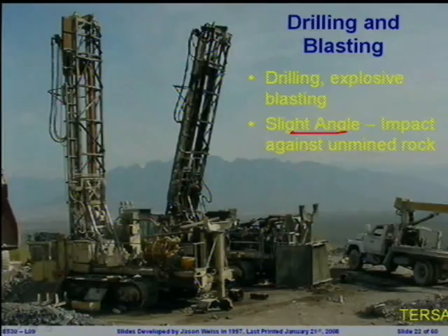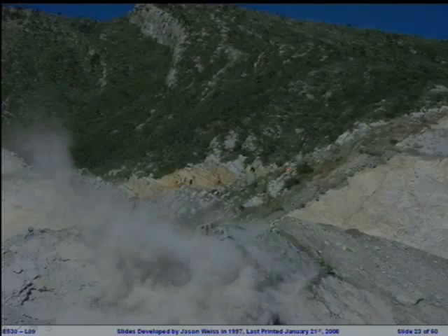rock up. I will tell you that at the quarry that I worked at on one particular occasion, the drilling crew had the angle all right, they had the direction all wrong, and it's a big cleanup issue when you project the rock to blast across the quarry. There it was about a $2 million cleanup issue, not only from cleanup, but the plants and the trucks that they crushed in the process of doing it. So being cognizant of what's going on is incredibly important.